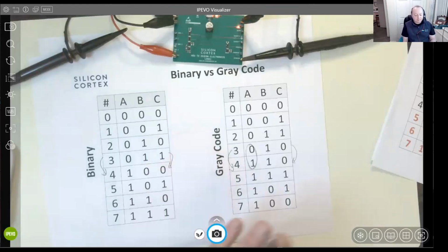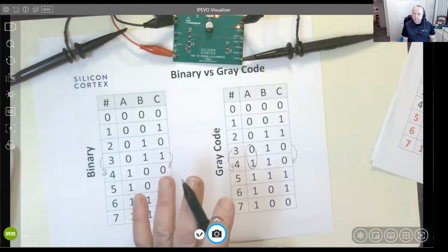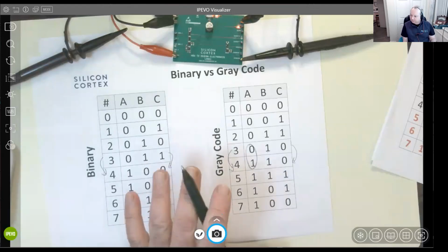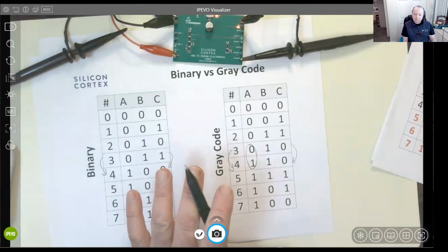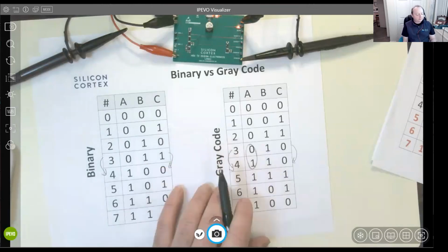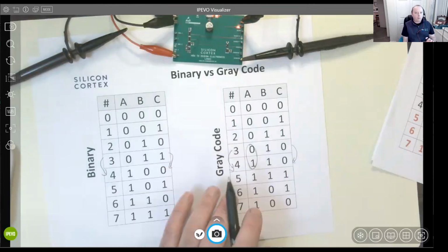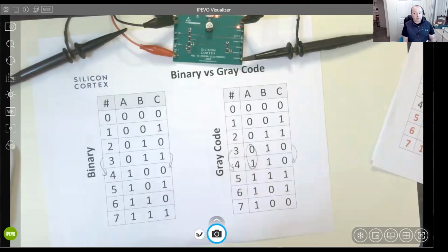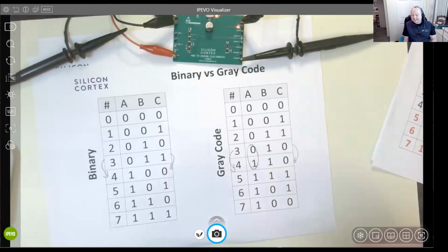When they tested it for EMC, they found the equipment was susceptible to radio waves of a certain frequency. Back at Pinewood, they did an investigation, and half an hour before the pyrotechnics blew up, somebody had ordered a taxi. And the rest you can work out: the taxi arrived with his slightly illegal ham radio. Yes, I'm here. Off went the explosion.